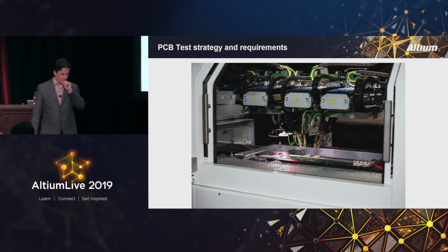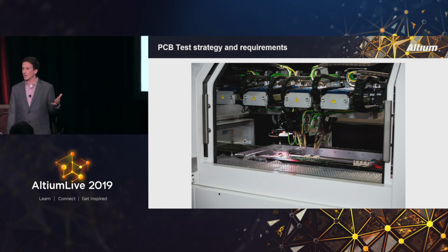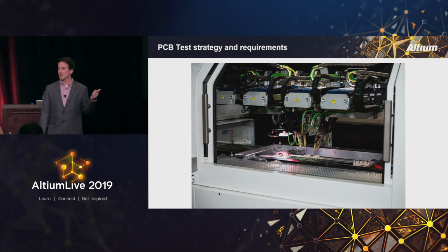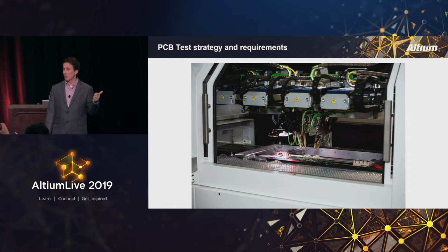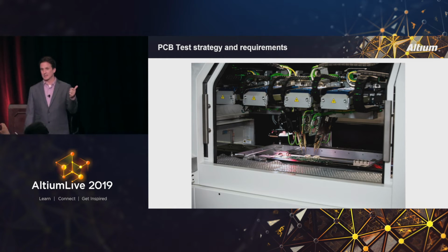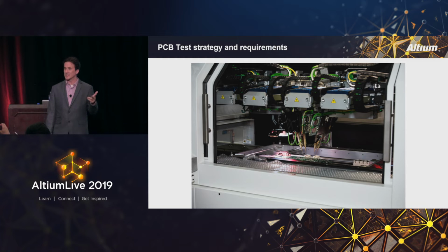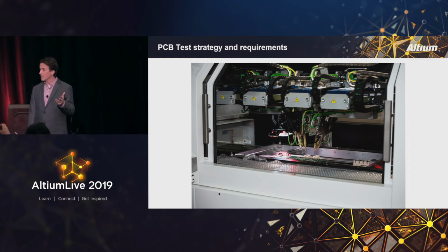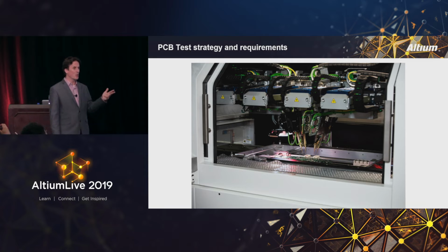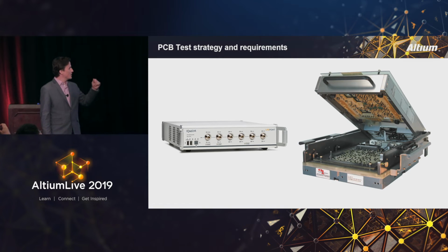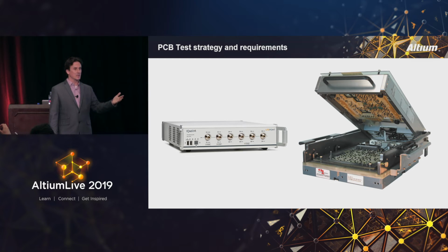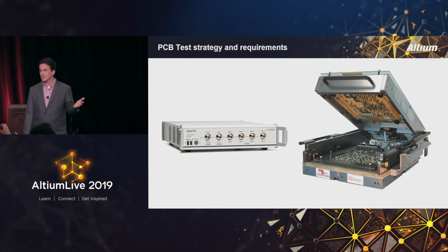Okay. So PCB test strategy, if you don't have a good one, this is most likely the machine that you're going to end up on, which is a flying probe. It's expensive, it's less reliable, and it takes a long time. So don't put off making a decision. What you need to be doing, in a high volume application, which is what we're looking at in this talk right here, is designing something so you can use a bed of nails.